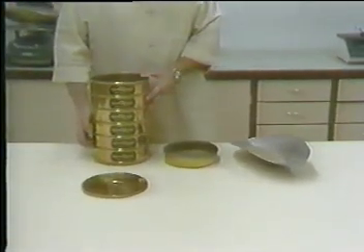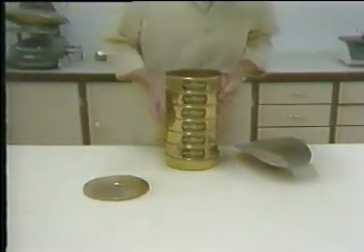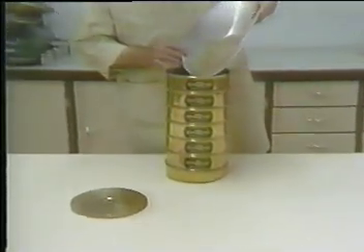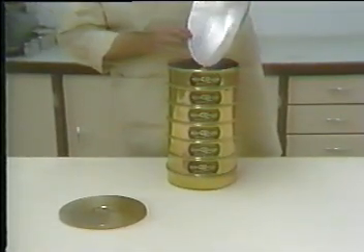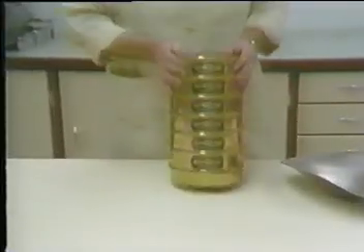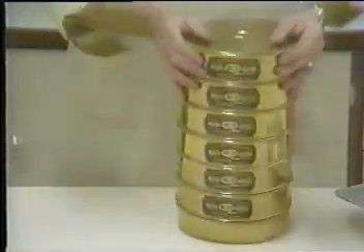The procedure is as follows. Starting with a bottom pan, nest the sieves in order of increasing size of opening from bottom to top and place the sample in the top sieve. Cover the top sieve to prevent loss of particles during agitation. Agitate the sieves by hand or by mechanical apparatus. The use of the hand method is not recommended when the size of the sample is 20 kilograms or larger.